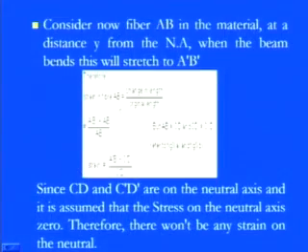So now our main intention is how the deformation can be measured and how we can relate this strain to the stress component. The important feature here is that whatever deformation is there due to this bending moment is always elastic deformation, so we can straightaway apply Hooke's law, in which the stress is proportional to strain. Since the bending moment is applied, we have the bending stresses, which are proportional to the strain component. So our main focus is on the strain in fiber AB, and what kind of deformations are there along that path.